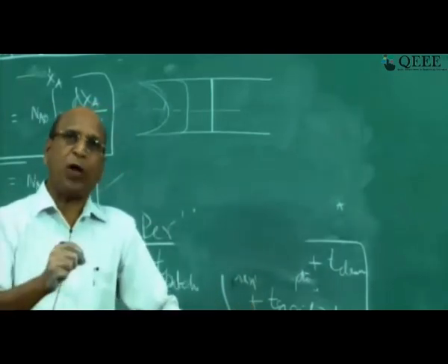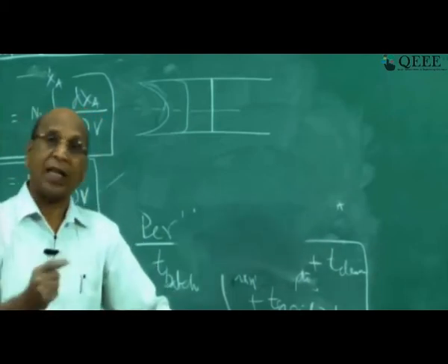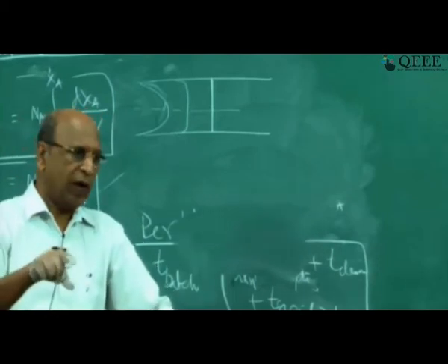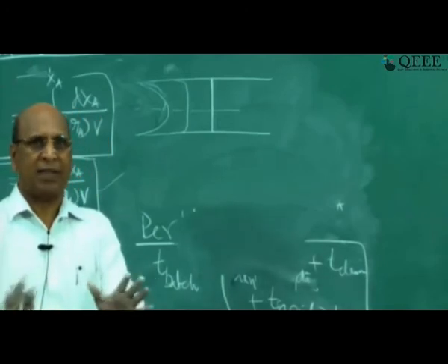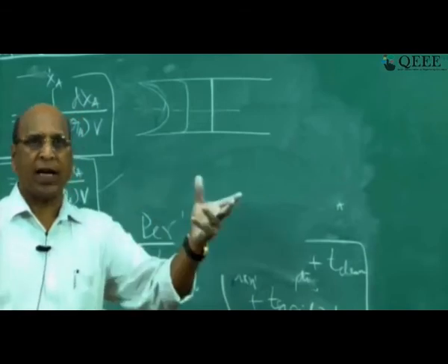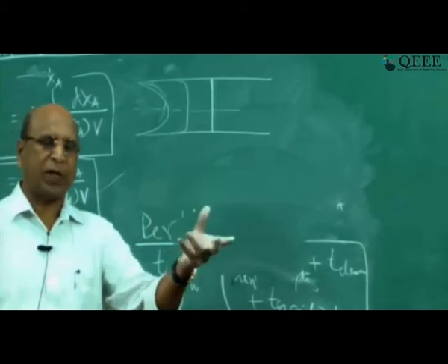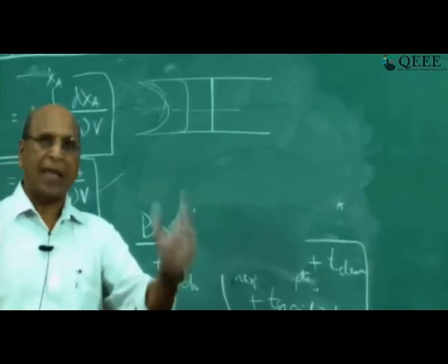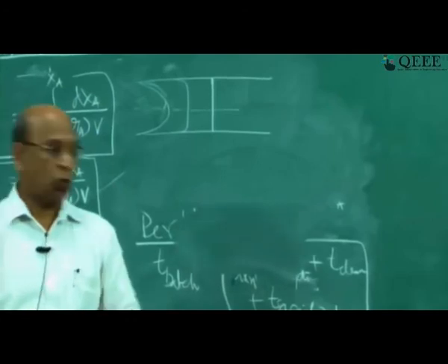That is why plug flow reactors can be widely used for gas phase reactions, or even liquid phase reactions where the time of reaction is very small. We don't differentiate between gas and liquid. Whenever you have very fast rates, or the time required for conversion is very small, then we use plug flow reactors. That is very good. Very good question.